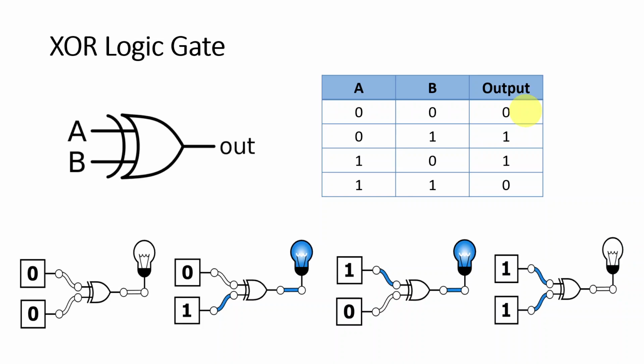So the third logic operation is the exclusive OR logic operator. This is somewhat hidden in day-to-day use, because when we say OR, sometimes we mean OR and at other times we mean XOR. In normal OR operation, when both are 1, we also take it as 1. But when it comes to exclusive OR, the two inputs must be exclusively different. Therefore, this 1-1 combination is also considered as resulting in 0 or false.